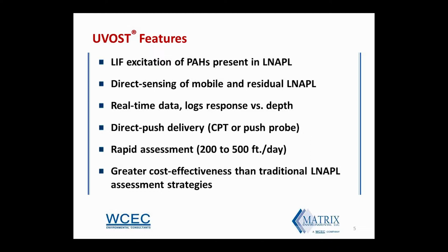Let's look at the basic features of the UVOST. As I just mentioned, the UV laser excites the PAH molecules present in LNAPL, causing the PAHs to fluoresce. This is a direct sensing tool, meaning that it collects data from immediately adjacent soil and whatever fluid is present in the pore spaces of that soil. Unlike some traditional site assessment tools, it can identify the presence of mobile and residual NAPL, although it cannot differentiate between the two. Data are logged in real time, giving an instrument response versus depth.